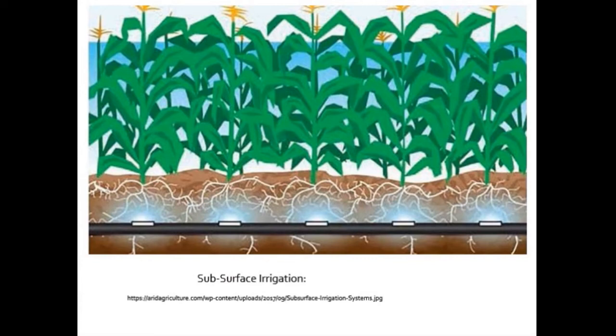Subsurface irrigation requires little field preparation and labor. It entails minimum evaporation loss and surface waste. The use of subsurface irrigation is limited because it requires certain soil conditions. That is, the soil is permeable in the root zone, underlain by an impervious horizon or high water table.